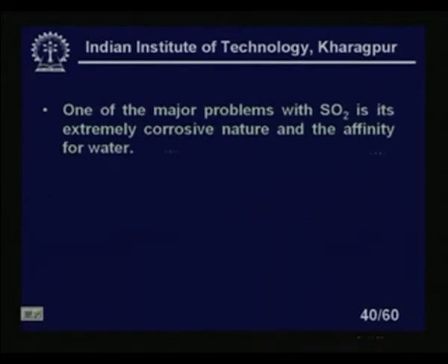One of the major problems with sulfur dioxide is its extremely corrosive nature and its affinity to water. As I told you, NOx is not that corrosive, but sulfur dioxide is corrosive in nature as well as having an affinity to water. So we should take higher precautions when analyzing sulfur dioxide than nitrogen dioxide. For nitrogen dioxide, if I remove all the water by some dryer or other means, that is fine.